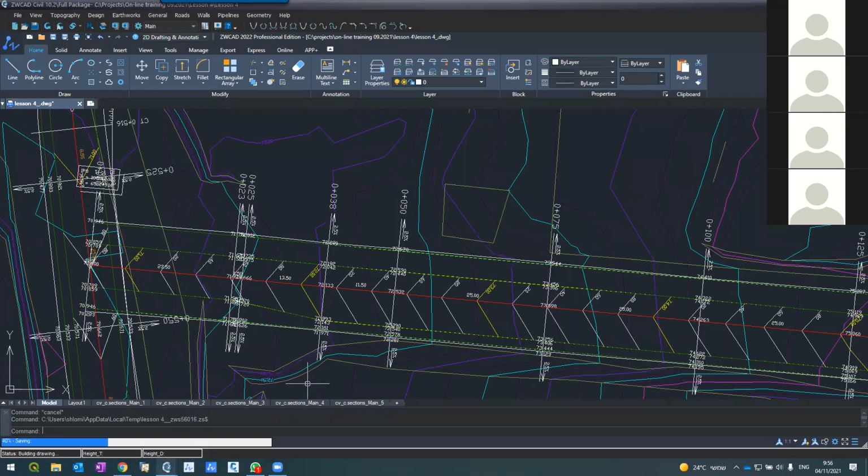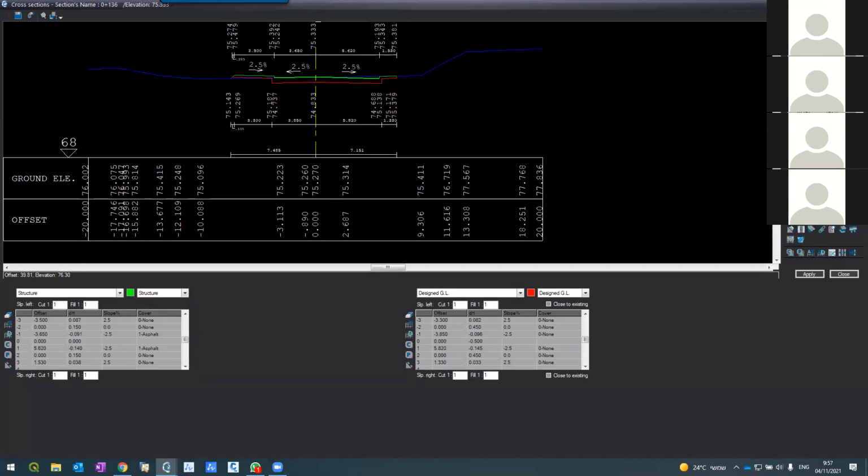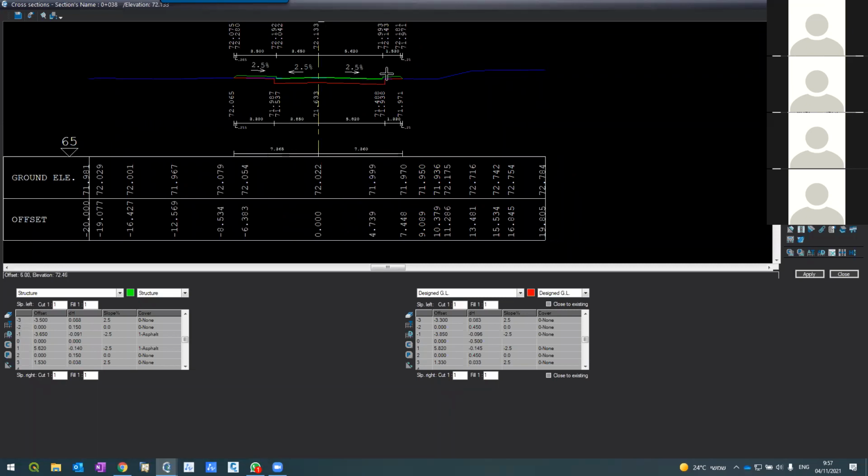So again, the problem was that we had an intermediate cross section like this one, let me mark it as intermediate, and this one that didn't have a ground level, and therefore the system didn't know what to do, so it just gave a template of ground level, and then the width was not accurate. So what I did, I took the topo for all the sections and rebuilt, and that solved the problem.